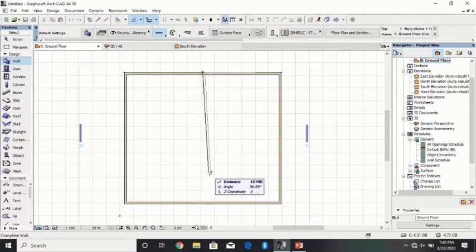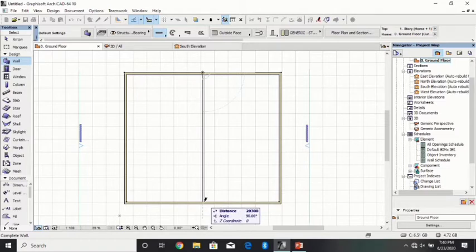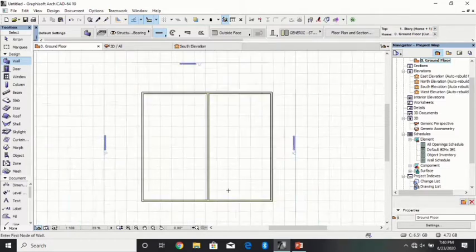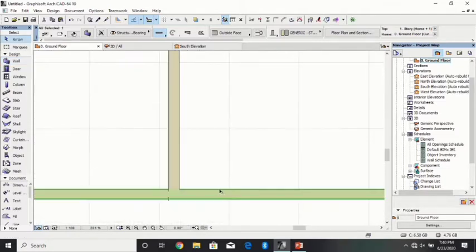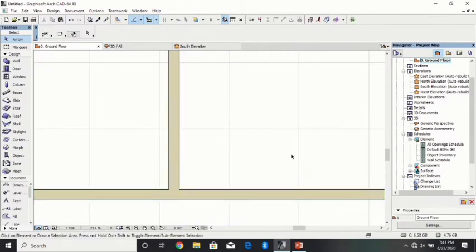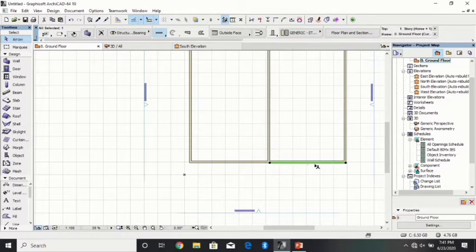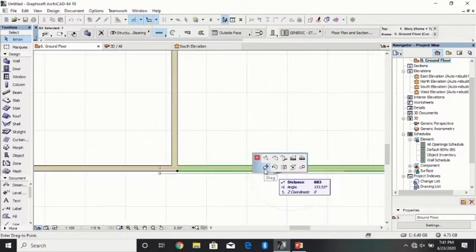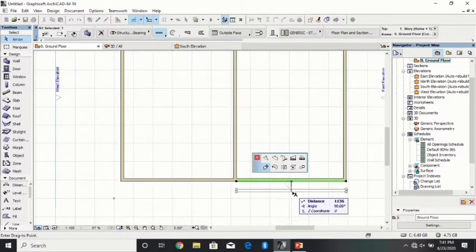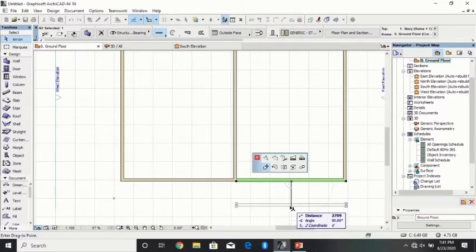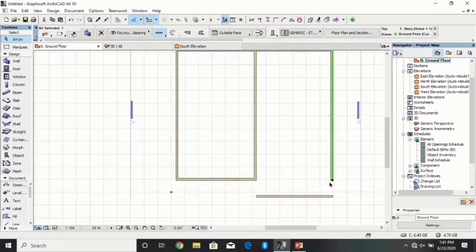Now we're focusing on the internal walls. To cut a wall, highlight the wall you want to cut and click on your split tool, then draw a vertical line along where you want to divide and get separated. If you watch my previous videos, you see where I explained that the tools for every object is different. Now we're trying to adjust this wall down, bringing it to meet each other. Okay?